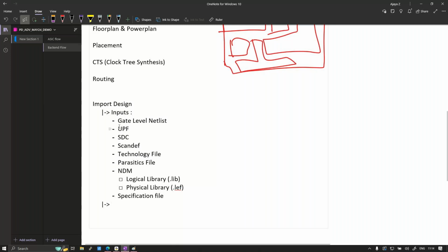All this information or files will be provided through some commands and stored in a file called a TCL file, a tool command language file. Through that tool command, I'll source it directly. All the information is saved. I'll just source it, and I will observe the log file only. Once this file is completed, I'll start observing the log file and reports.